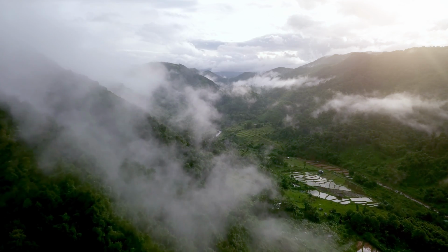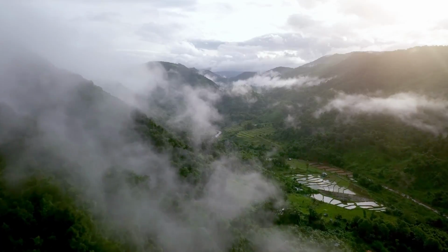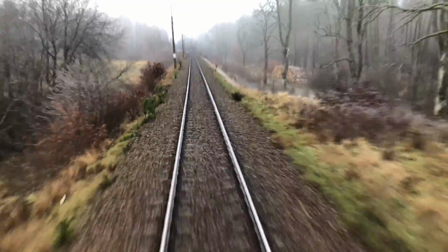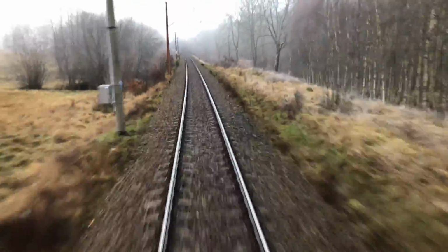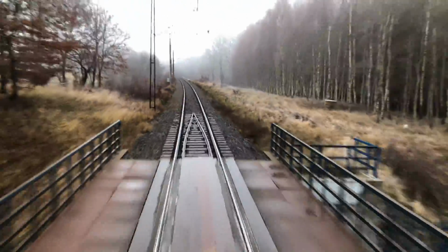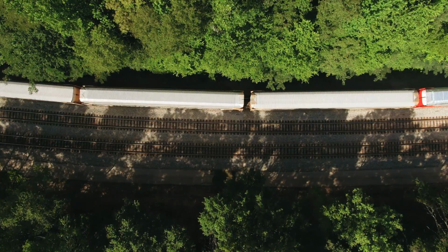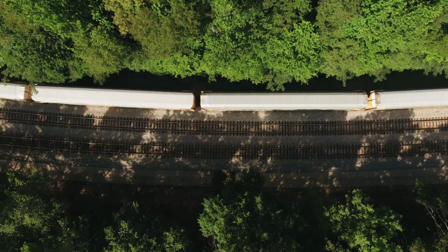Even if the bridge itself is sound, the interface with the surrounding track is where geometry issues can really start. You're going from floating formation to a fixed structure. This change causes voiding or top faults at the interface, sudden changes in settlement behaviour of the track, twist and other alignment faults. Transitions need designing.